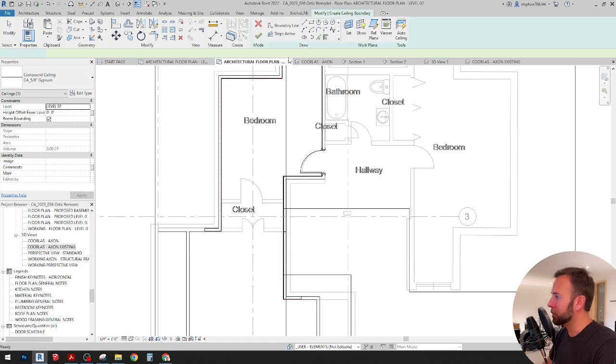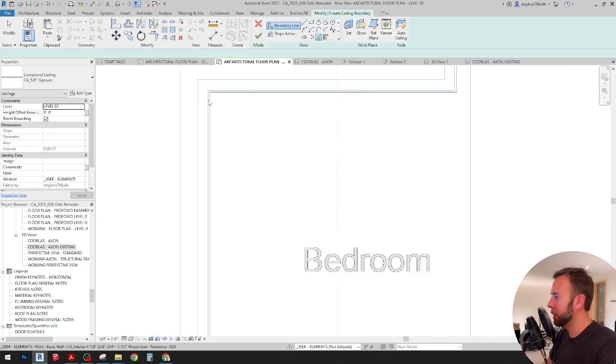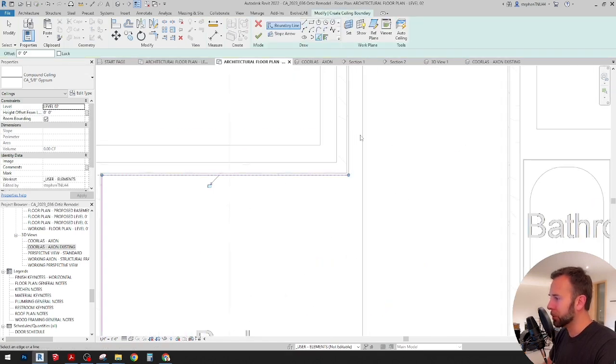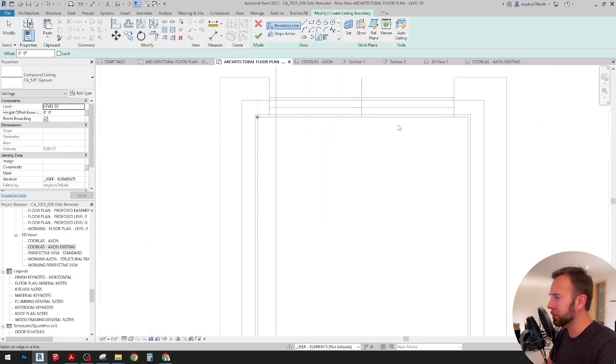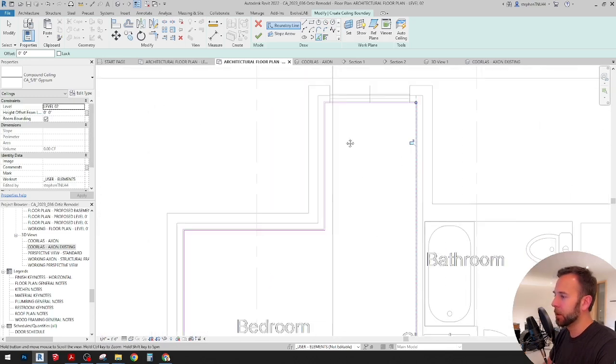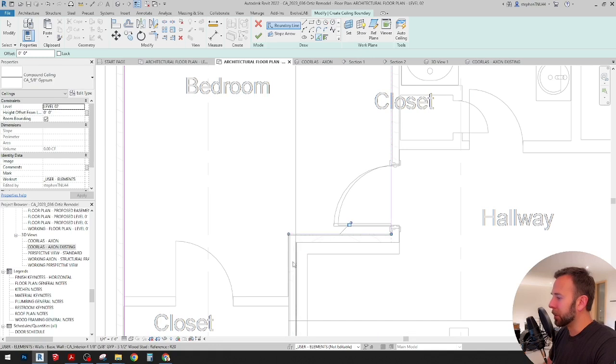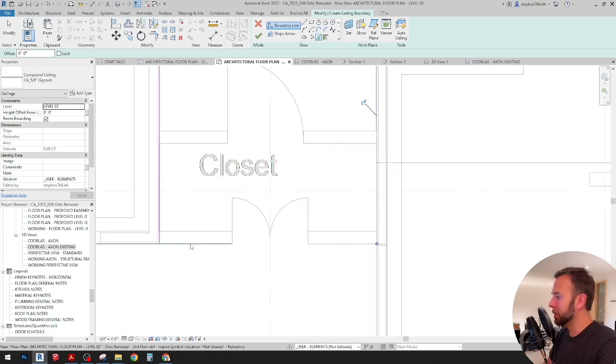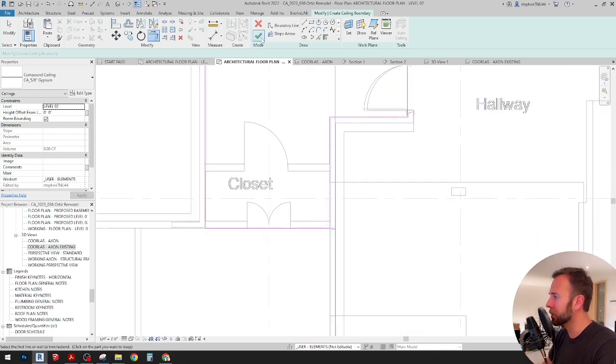and I'll do sketch ceiling. Take this, and I usually just do my ceilings to the inside face of the drywall. Just chase it around the perimeter there, and this might get a little goofy at the edge there when it does soffits. You have to make sure that the wall, that is a soffited wall, rises just above the 5/8 inch plane for the roof. We'll take a look at that in section, but that should be good. Level 2, 5/8 inch gyp ceiling.